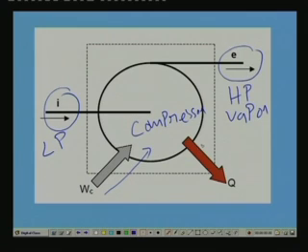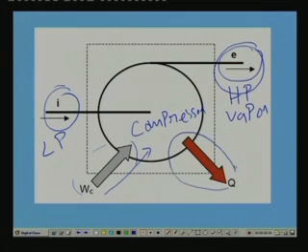If you look at the energy flows, you have the energy flow by means of mass flow at the inlet and mass flow at the outlet, and you also have energy input by means of the work input, and the energy interaction between the system and the surroundings by means of the heat transfer rate. So, this is the system and this is the control volume, and to this we apply the steady flow energy equation.